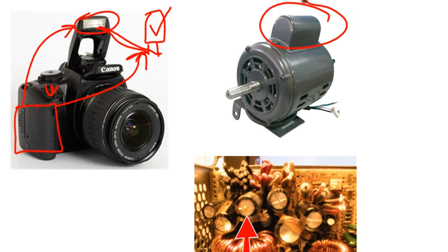For your refrigerators and for motors and for industrial and commercial applications, oftentimes we will have these heavy-duty motors that are connected to a strong load. And so when you want to start up the motor, if you just apply energy to these leads without a capacitor, this motor won't be able to run. So if you want it to be able to start up, these motors use what's called a starting capacitor, which usually you see as an extra bump on the round cylinder for the motor.